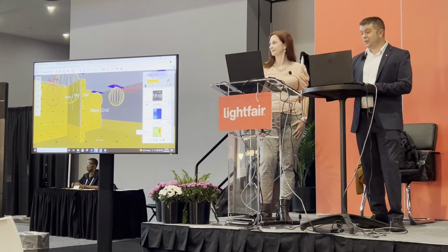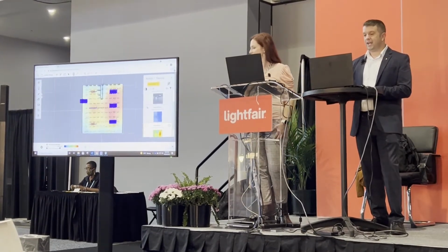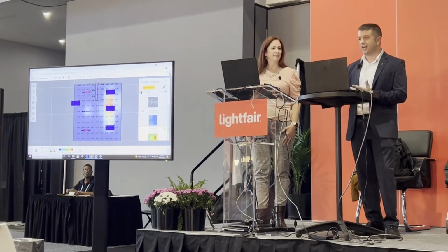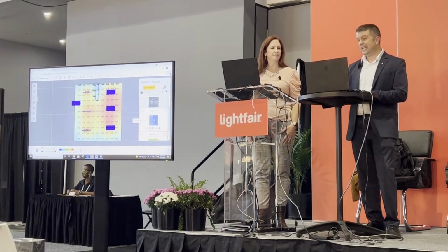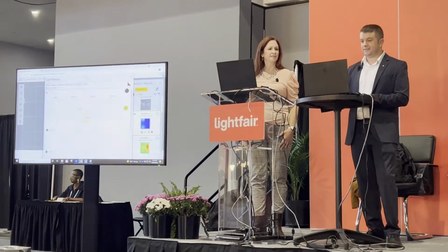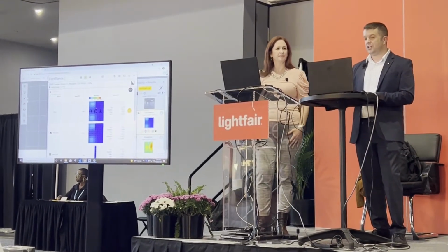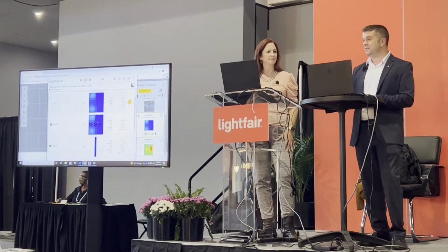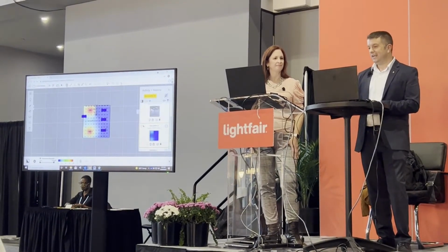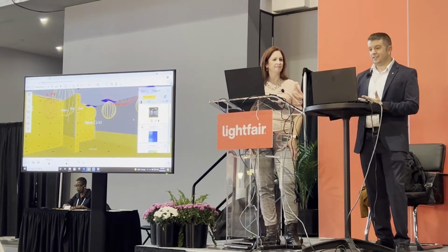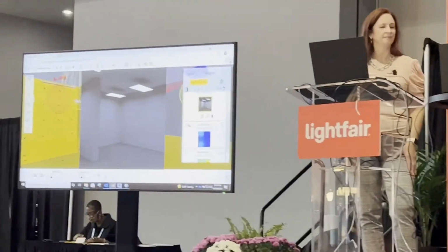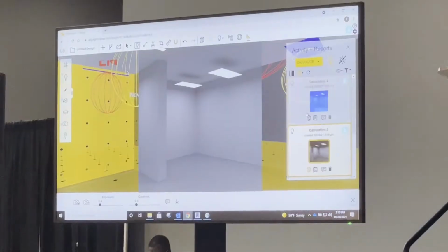So it looks like some of the calculations are done. This was my normal lighting calc. I've got it here. I can change any of these parameters just with the slider on what I'm trying to convey. I've got my emergency calculation here. I can do a little report. It pulls up all the calculation points that I have in this model. It gives me all of my values for it. It shows me what they look like. I've got my renderings here with this overlay. Again, this is all adjustable. I can make it look however I want.